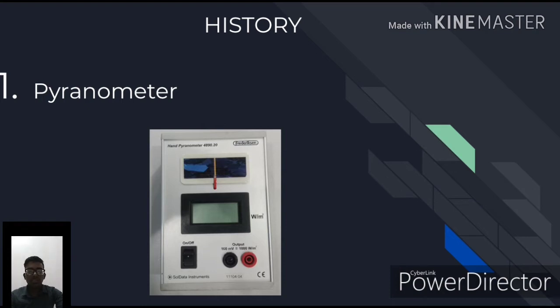Photodiode-based pyranometers are equipped with a photodiode, optical filters or diffuser, and a housing dome. The photodiode is the sensor, and the current it produces is in proportion to the irradiance. A photovoltaic pyranometer uses its photovoltaic cell to measure the irradiance of sunlight. Guys, do you know how a pyranometer measures irradiance? It's actually the temperature difference between the active and passive junction that generates a small electrical voltage to provide the solar irradiance measurement.